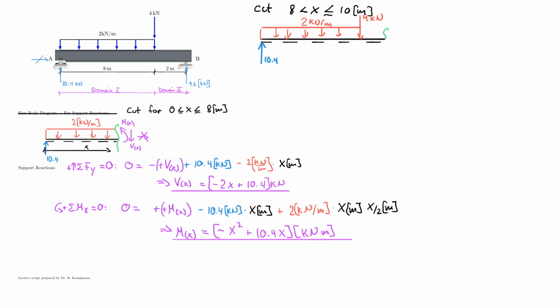Let me now cut the system right here, and let me of course explain that we have a function that goes in this direction with x, and I have to bring in my internal forces. I have the moment and the shear force to worry about, m of x and v of x. And now you have to be careful because your x starts at 0 right here, right? So what I will do now is express two lengths.